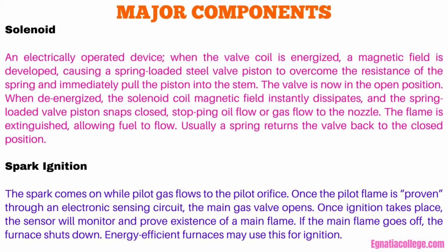When de-energized, the solenoid coil magnetic field instantly dissipates, and the spring-loaded valve piston snaps closed, stopping oil flow or gas flow to the nozzle. The flame is extinguished, stopping fuel flow. Usually a spring returns the valve back to the closed position.